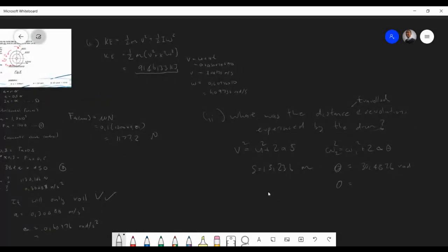So you just divide that. And of course, the reason what we're trying to say here is that if the drum was initially at that point, it'll go once, twice, 3, 4, nearly 5 and stop. It spins that amount of times. That's what it is, 4.8552 revolutions. You'll pick this up also when you're dealing with brakes.